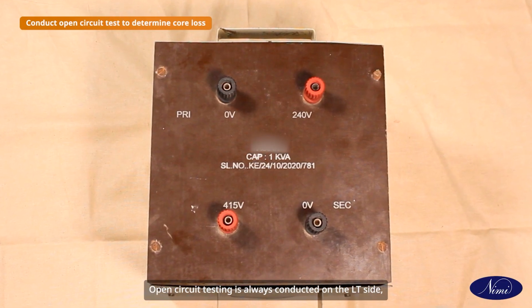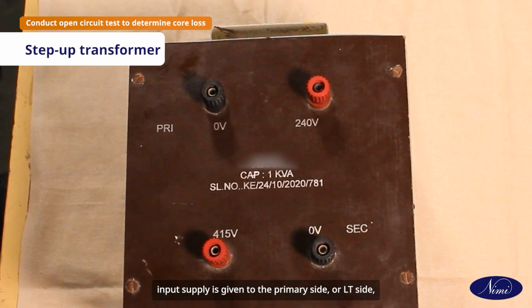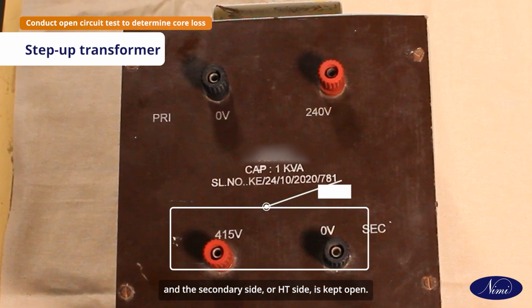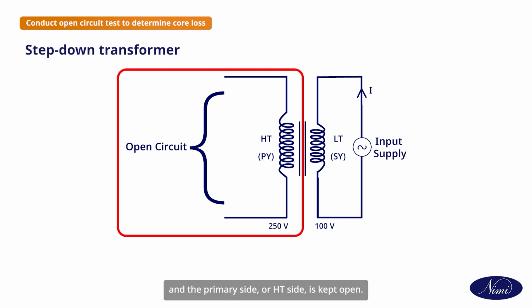Open circuit testing is always conducted on the LT side, that is, meters and the input supply are connected to the LT side and the HT side is kept open. In step-up transformers, input supply is given to the primary side or LT side and the secondary side or HT side is kept open. In the case of a step-down transformer, input power is given to the secondary side or LT side and the primary side or HT side is kept open.